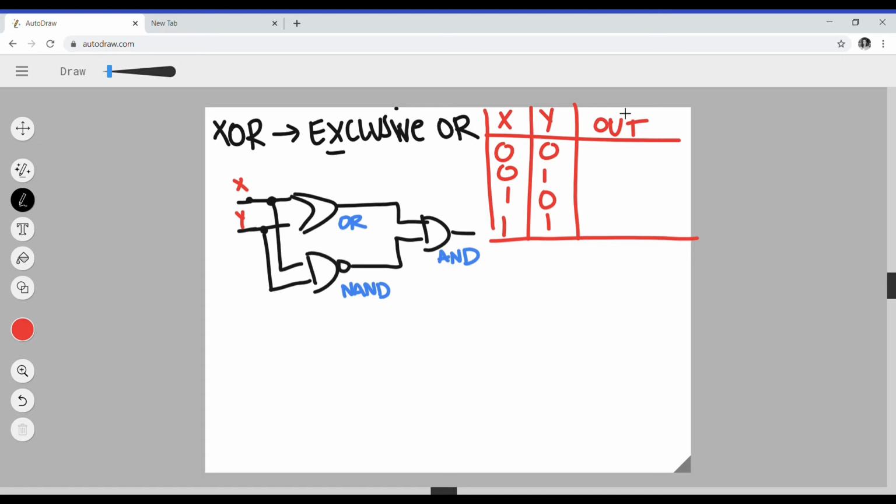We'll go ahead and start off with the first 2 combinations where we have a 0, 0. So let's start off with the OR gate. 0, 0 fed into an OR gate will give you an output of 0. That means both switches are open in a parallel circuit, so the light bulb will not turn on. And for this, we'll analyze it as an AND gate first, and then we'll flip the bit. So 0, 0 through a series circuit. Let me just write these down at the bottom for us to remember. Parallel, we'll have 2.